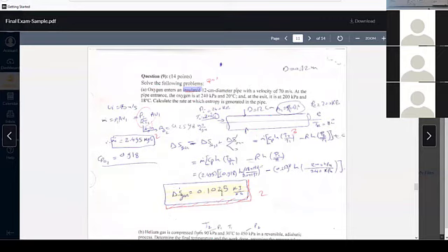The only thing here, in order to get some of the information, is using mass flow rate, m dot equals rho A V, and we have the ideal gas rho equals P over RT to get information like pressure or something else. So this is the only thing. He gives you mass flow rate somewhere, or he asks about mass flow rate. We need mass flow rate for this equation. So you can get the mass flow rate using this equation. The units should be kilojoule per kilogram Kelvin, multiplied by mass flow rate, it becomes kilojoule per Kelvin second, which is a rate.